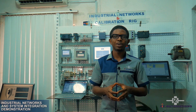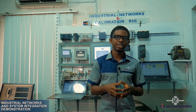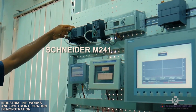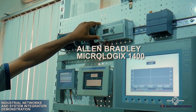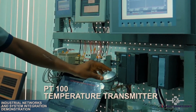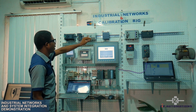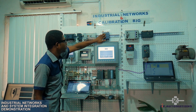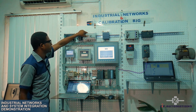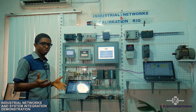Today I'll be taking you through our industrial networks and systems integration automation rig at our training facility here in Lagos. Here I have a Schneider M241 PLC, an Allen Bradley Micrologix 1400, a Siemens S7 1200 PLC, and a PT100 temperature transmitter. The PT100 transmitter is connected to our S7 1200 PLC. The S7 1200 PLC reads the data from it and then transmits the data to the Micrologix 1400 and the Schneider M241 PLC over a Modbus TCP network.